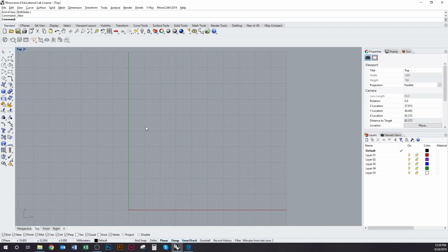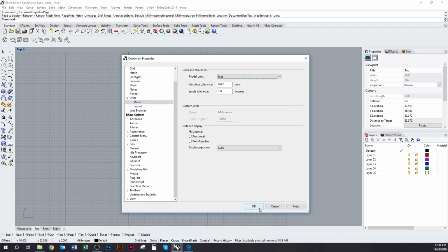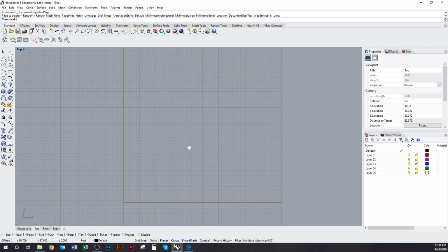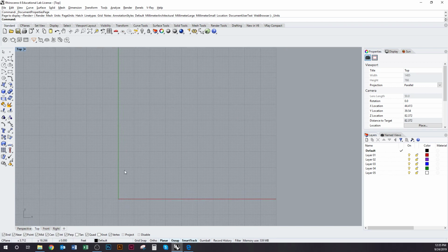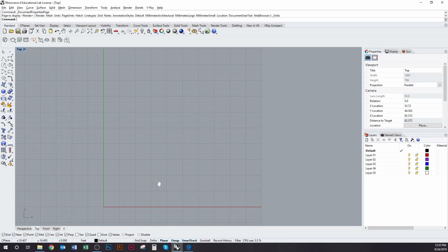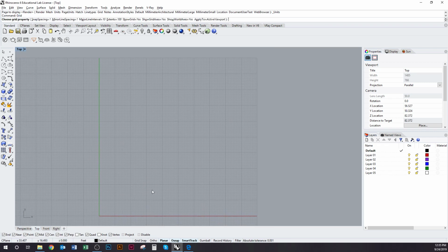So first I'm going to go into Rhino. I want to change my units. I'm going to work in feet. Unless you're working on a scale model in Rhino, you almost always want to be working at the exact scale of your object, at full scale, in other words, and then scale as you draw, or export, say. I'm just going to turn my grid off.